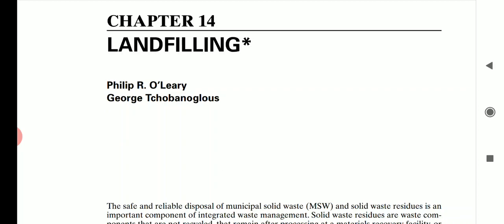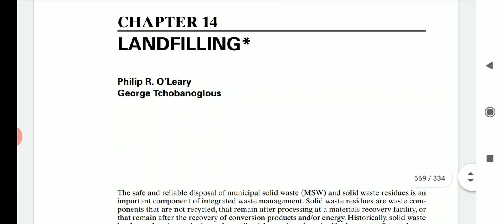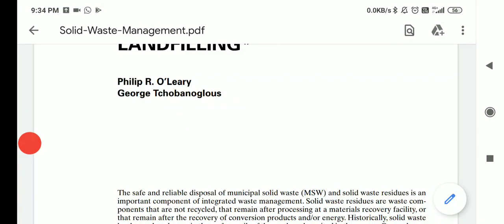But landfilling is also the same thing, except that engineering technologies are used in a dump site. If you prepare the dump site using some technologies, then it is called landfilling. For example, in a dump site we do not prepare anything, we just dump on it. But in landfilling, liners are provided on the earth surface, and the gas produced from the decomposition of solid waste is collected with the help of vent pipes.